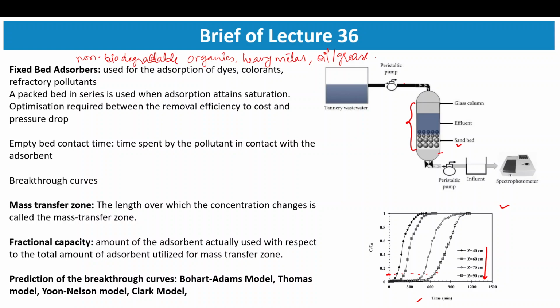As the water containing the pollutant passes from top to bottom through the bed of adsorbent, initially the entire adsorbent bed is free of the pollutant, so maximum removal happens. Very low, or majorly zero, concentration is obtained till a certain point.